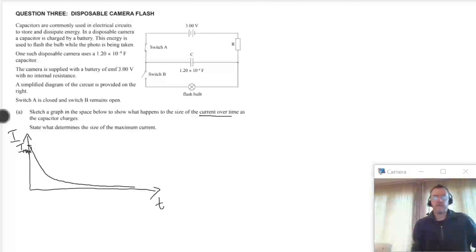The current is going to be driven by whatever the values of the other components in this loop are, but as current tries to flow, it starts building up in the capacitor here, and a voltage in the capacitor builds up that opposes that current, which means that the current slowly drops over time. And if we wanted to, we could throw some extra details in here, like our one time constant line, and that this is 0.37I, but you don't need it. That graph alone, labeled up properly, was worth a...